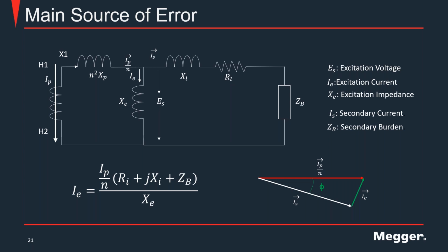So there is no straightforward answer to this one, because the IEEE standard doesn't have a recommended timeline on how often you should test CTs or metering CTs. But the way I would answer this question is that whenever metering CTs are used for revenue purposes, you obviously want to make sure that they are reading accurately and are a true reflection of the power being consumed.